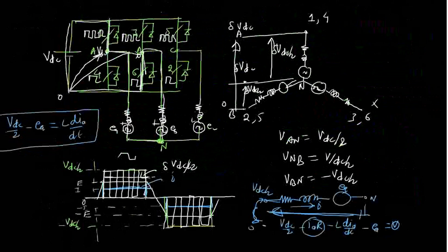Then further I explained the case that it is clear we use the 120 degree mode of operation of the inverter. I also explained what is the meaning of 120 degree mode of operation and what is the meaning of 180 degree mode of operation. All these things I explained to you. Then we also observed that in a particular Hall state, only two phases conduct like this.